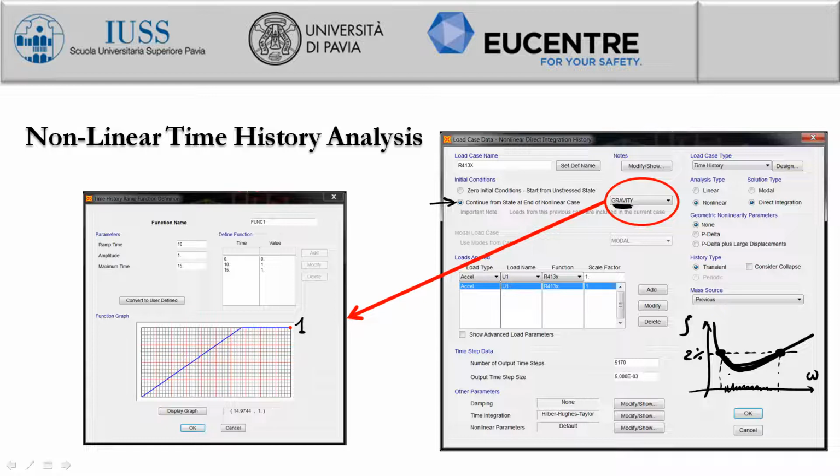For instance, with friction pendulum devices with double surfaces, we have P-Delta effects that are transmitted both to the superstructure and the foundation. What can you say about this? Is it important to account for the effects associated with this nonlinearity or not?